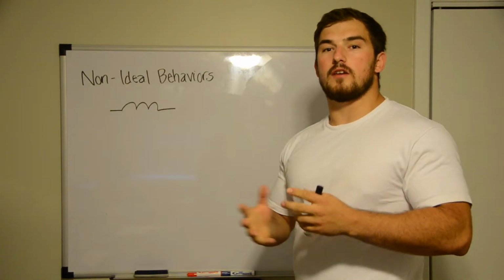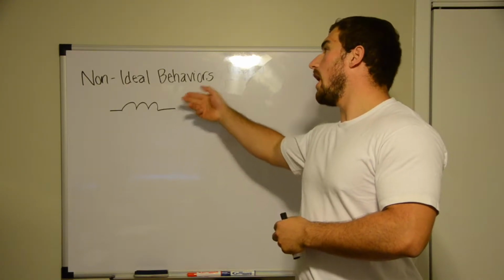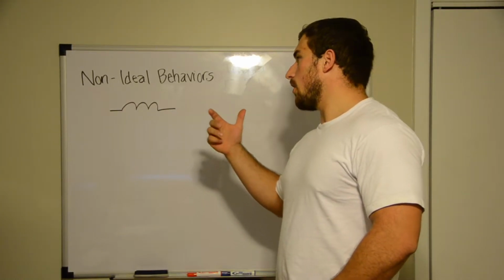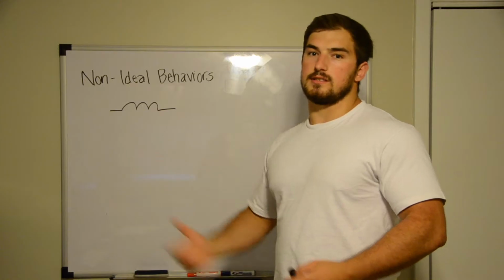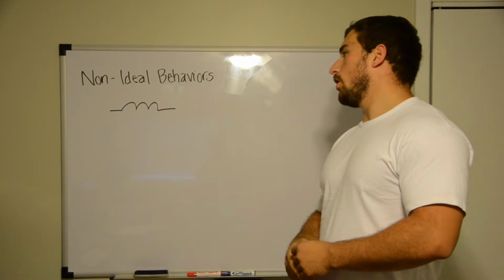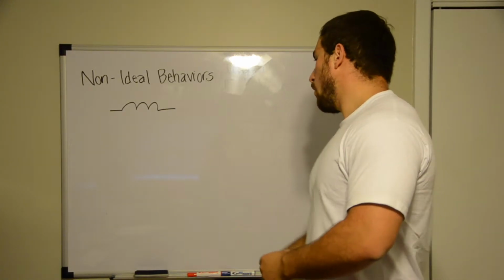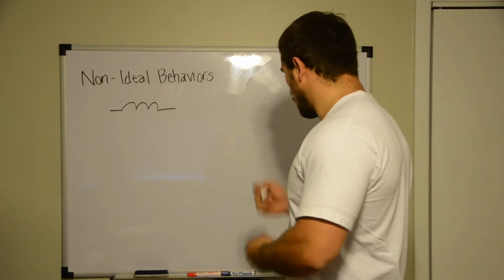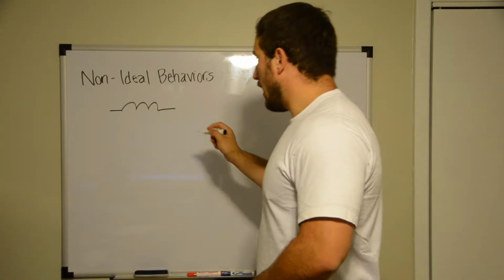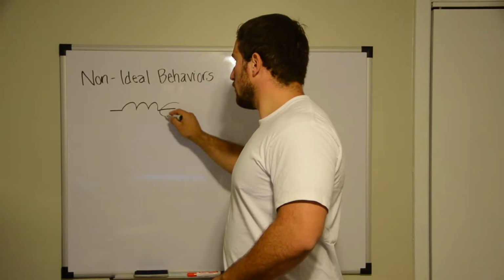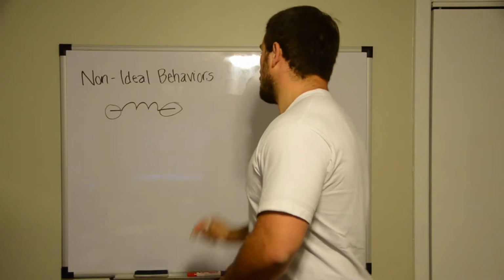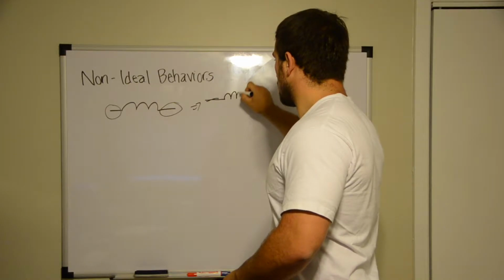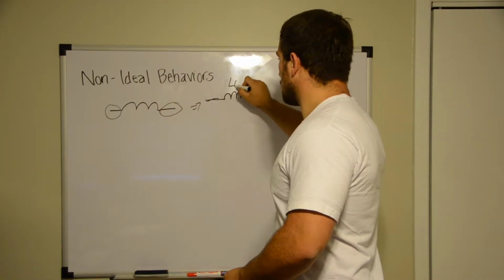Now we're going to move on to my favorite portion of this. We get into the non-ideal behaviors of lumped components. So basically, to start off with, an inductor seems fairly simple, but its equivalent model can get really complex. So from this model, we're going to depict the equivalent model for it. We're going to first begin by, as we described in the resistors one, we do get some inductance from the leads. So we're going to add an inductance from the lead.